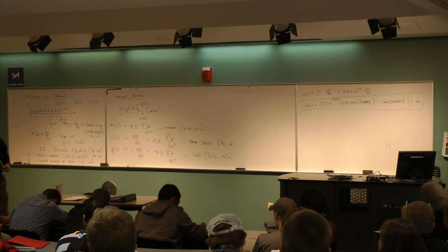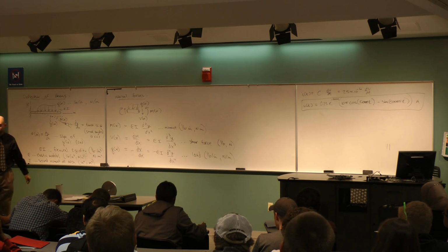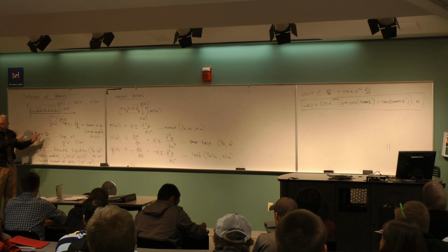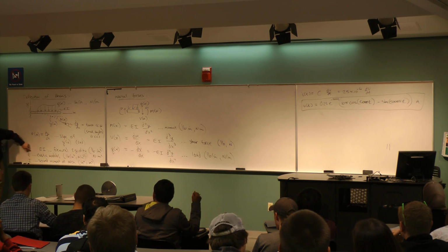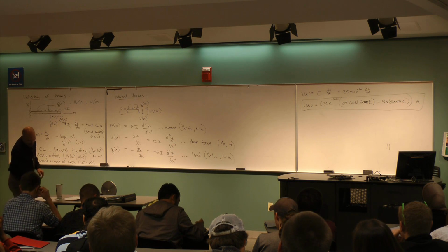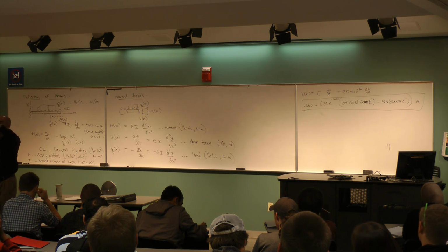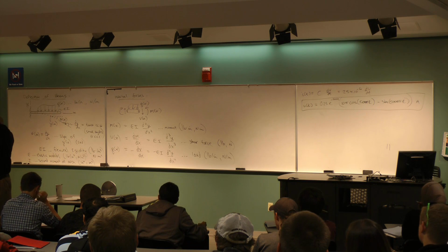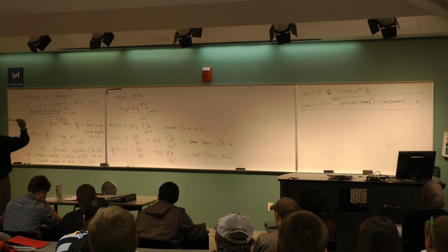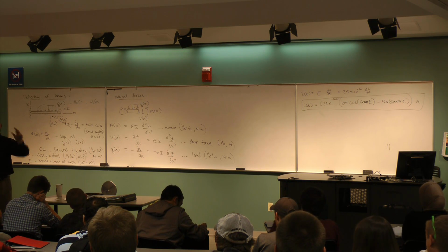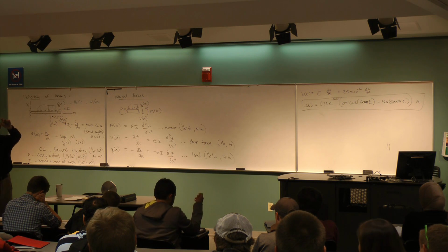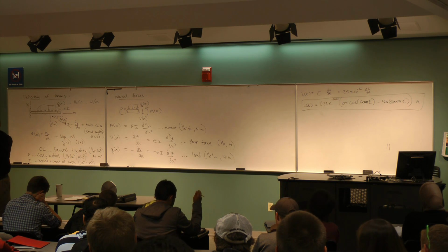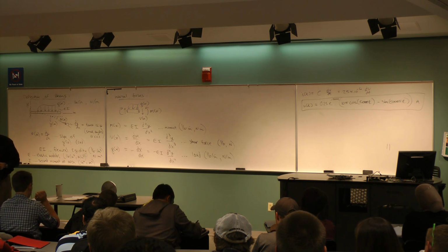And so this I is a property of the cross section. It's got to do with the orientation of the beam relative to the loads and the geometry. The E is whether or not this beam is made out of plastic, like this one, relatively small E, or it could be made out of steel, right? This exact same beam, same exact geometry made out of steel would be harder or easier to bend? Harder. A lot harder to bend. So it's a stiffer material, much bigger E. And that's the idea.